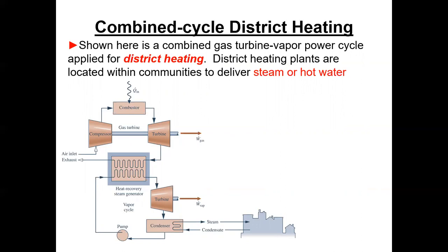That's what they're talking about here. I think we've talked about this before. What they're showing is just the Brayton cycle producing some electricity. Then we generate the steam. We come out of a steam turbine with enough temperature for this to be useful. If this is 110 degrees Fahrenheit, it's not hot enough to really be useful. So this has to be designed into the cycle.